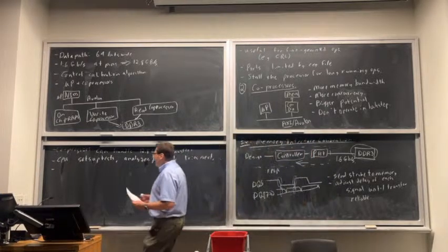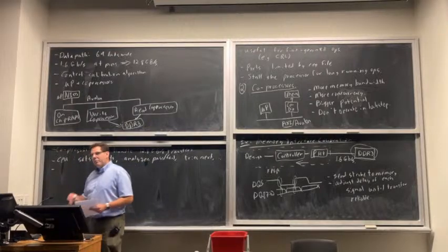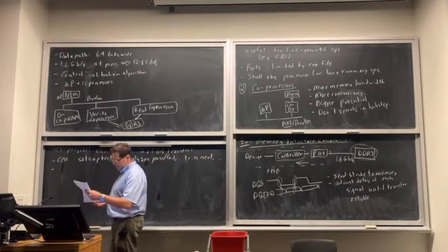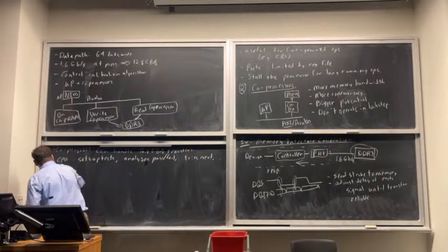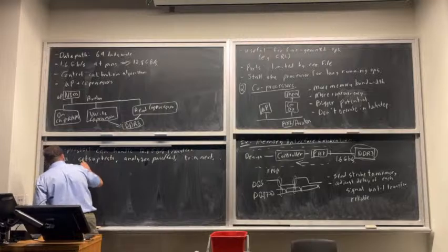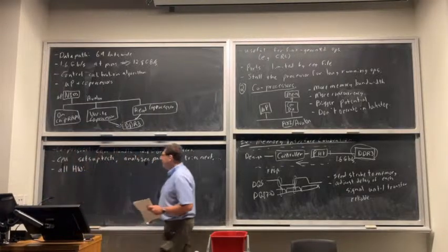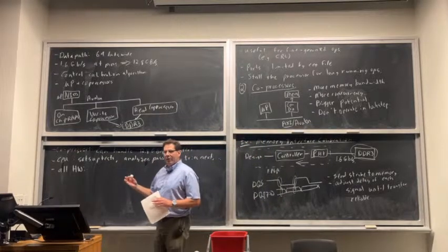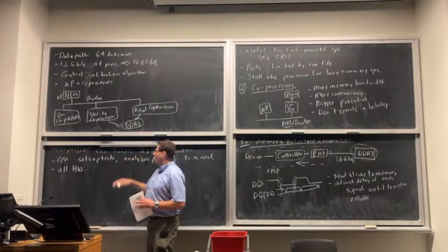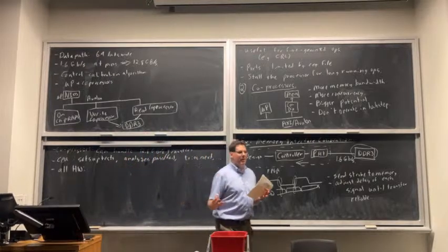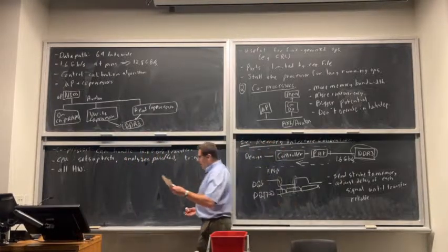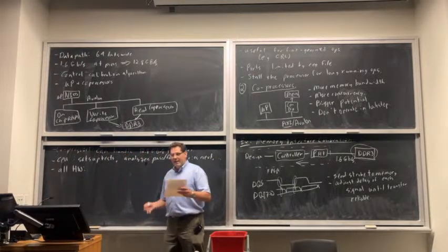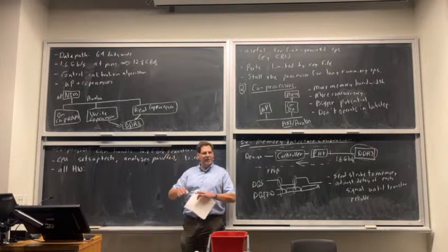So there was an older design, well, it was actively being worked on, but there's a design developed within the company already that was done using a different style. And this had been worked on for years, and it was all hardware, so it didn't use a soft processor. This project was moved to Toronto, and we switched to a soft processor plus coprocessor. So we actually have a kind of head-to-head comparison of two different styles. This all-hardware design had a state machine instead of a microprocessor to control this calibration.